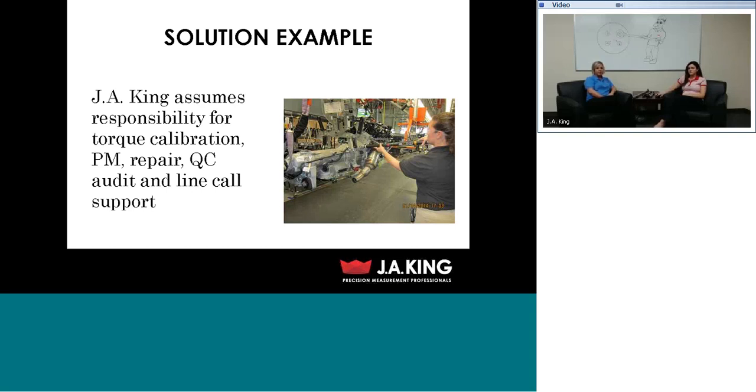At this point, the fastener is identified as loose, and a calibration technician is called to verify that the tool is still in calibration. The calibration technician confirms that the tool is damaged and the output is significantly lower than the desired output. An embedded repair technician responds to the line and identifies an internal transducer on the tool is damaged, causing it to read incorrectly. The repair is made line side and the tool is placed back into service. The calibration tech and the quality control tech immediately verify that the tool is repaired and in calibration.